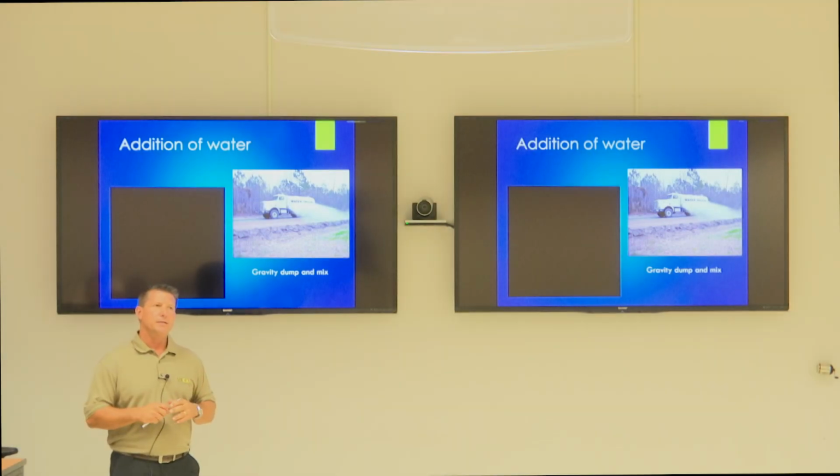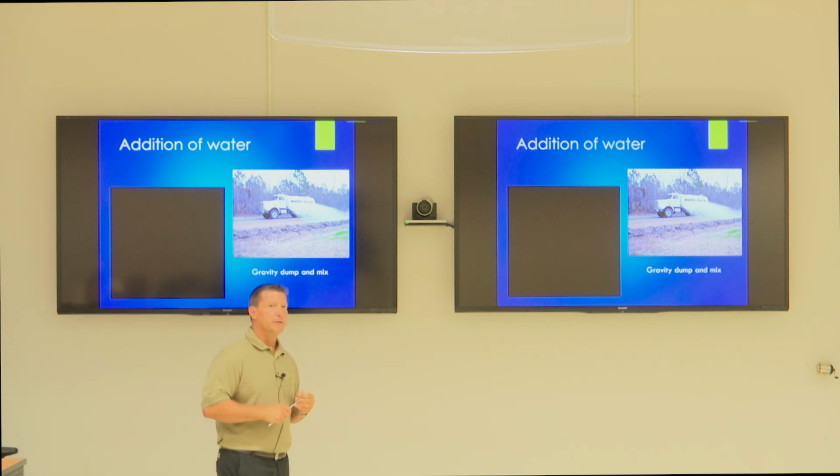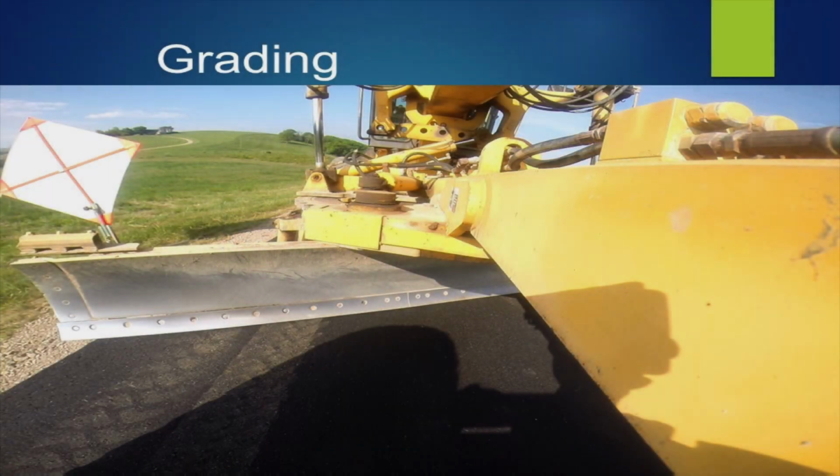If you go on a job site, typically you don't want to see dust. If you have the traveling public providing dust, now some of those days when it's 100 degrees and it's tough out there, you might get a little bit of dust from time to time, but in most cases, you should go out on the job site and it should appear as though the water truck has been there within about 15 or 20 minutes. Grading is absolutely critical.